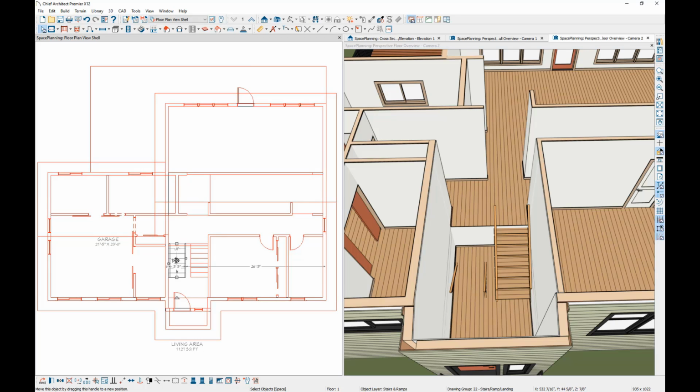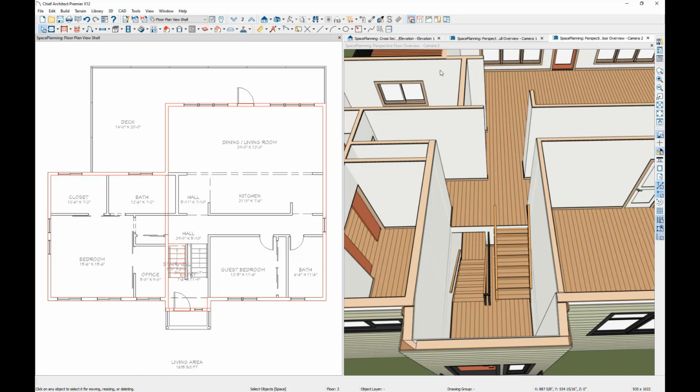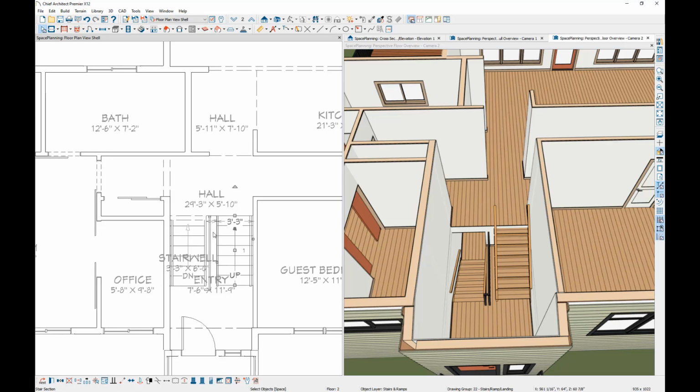The first way is you can select your stair that's causing the interference. And on the edit toolbar, we have an auto stairwell tool. If you click on that, you can see the program creates a hole that simply surrounds the staircase. That hole is generated on the floor above where the stairs were drawn. You can see it here. It's just adding railing walls to surround the stairwell.